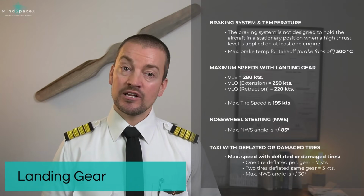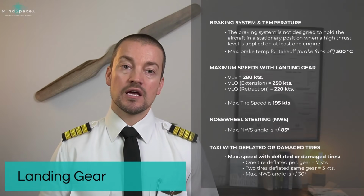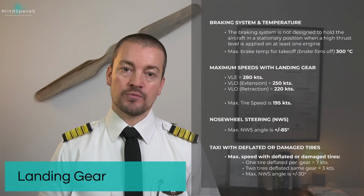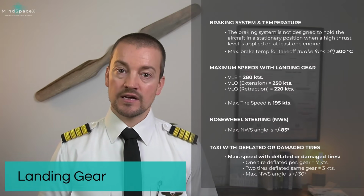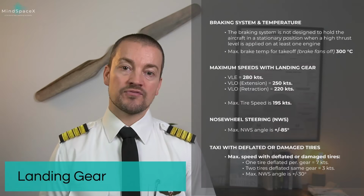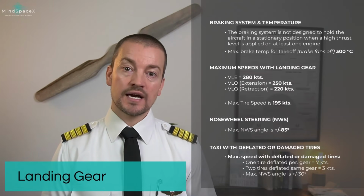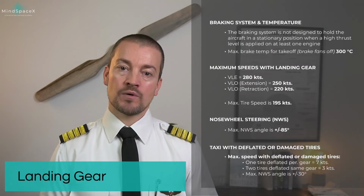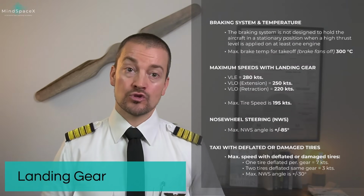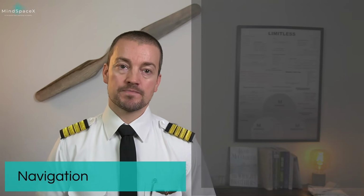Taxi with deflated or damaged tires also requires careful operation from the crew. Maximum speed with deflated or damaged tire: one tire deflated per gear, it's 7 knots. 2 tires deflated on the same gear, 3 knots. And then the maximum nose wheel steering is limited to plus or minus 30 degrees with deflated or damaged tires.